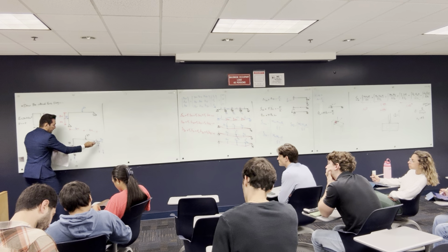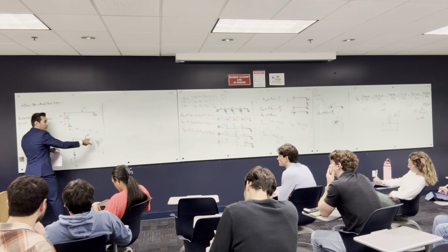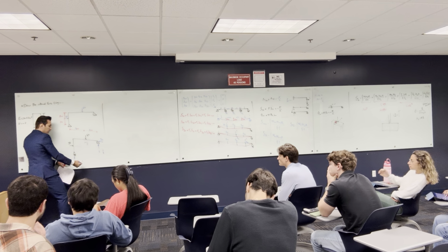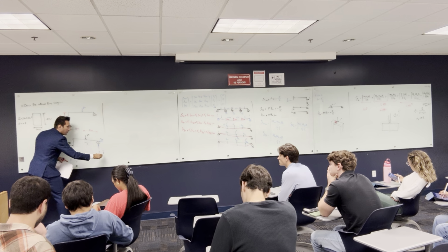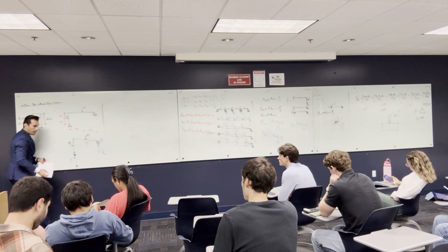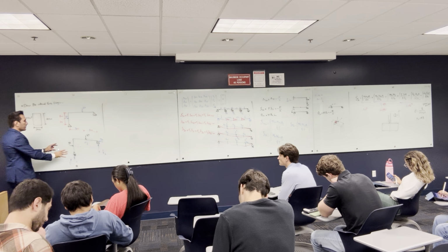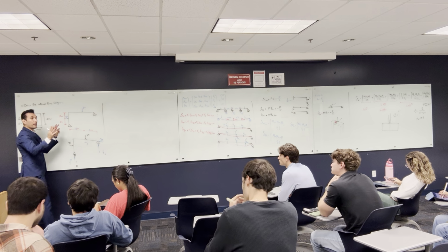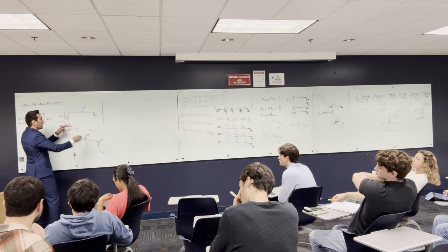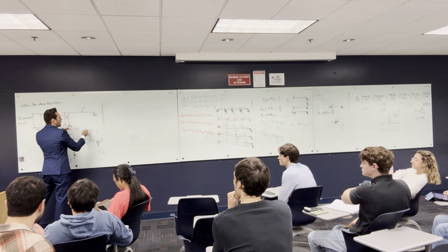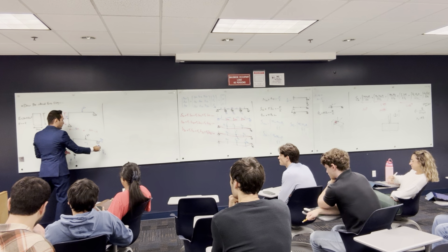So this is 3 multiplied by 2. So it's gonna give you 6, and you need another 6 ton-meter couple. So you need 1 here and 1 here. So what happened here is, I'm just trying to think as an engineer, how the moments are working. This 6 is gonna be divided equally because it's in the middle, 3 and 3.